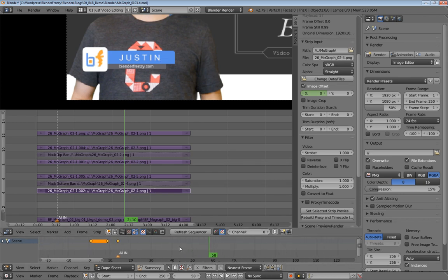So where's our dope sheet here? Select the bottom one. We're just going to reverse these two because this is where they change. So I'm going to select those two, Shift D to duplicate, move those all the way to frame 58. And let's zoom in here to make sure that is on frame 58.